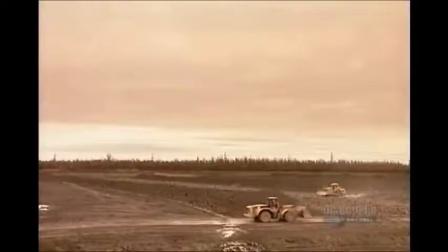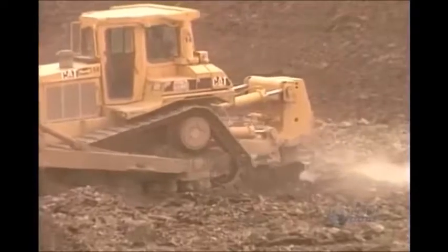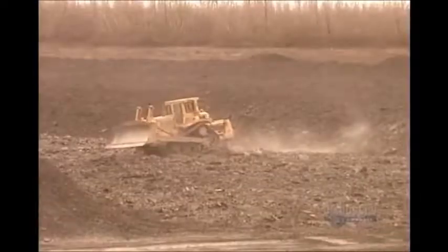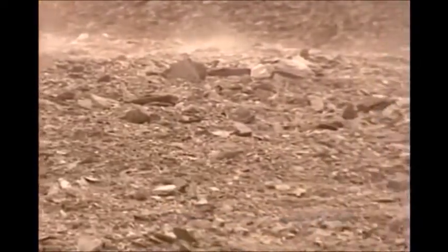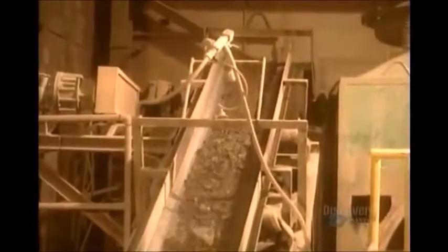Bricks are often made of shale, a lightweight rock that splits easily into thin layers. Quarry machines dig 40 centimeters down to expose the shale to the elements for 2 years. This weakens it, making it easier to process once it gets to the factory. A 4-foot-high stone wheel with a steel tire grinds the shale into powder. It grinds up 50 tons of shale per hour. A screen sifts out any pieces that need more grinding.